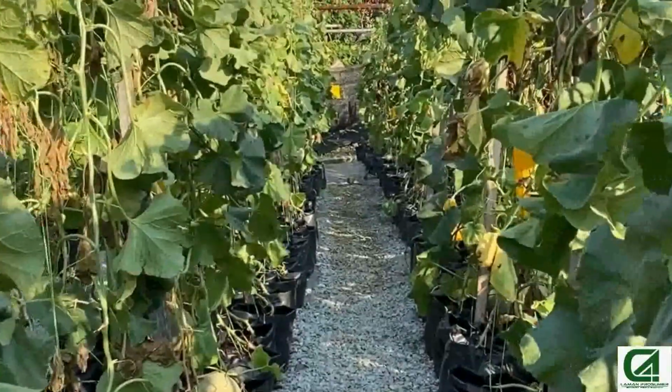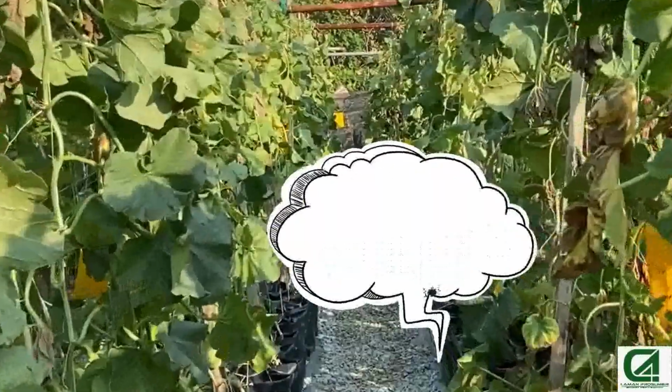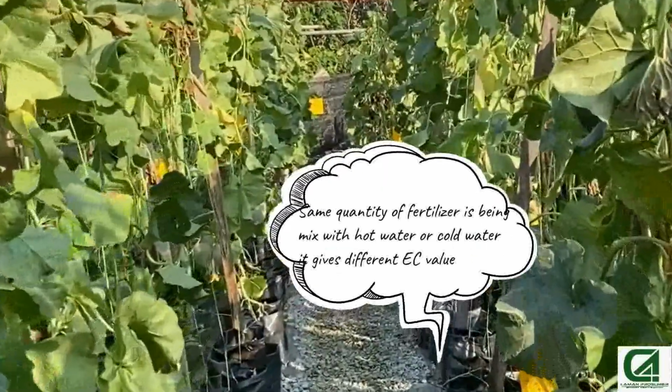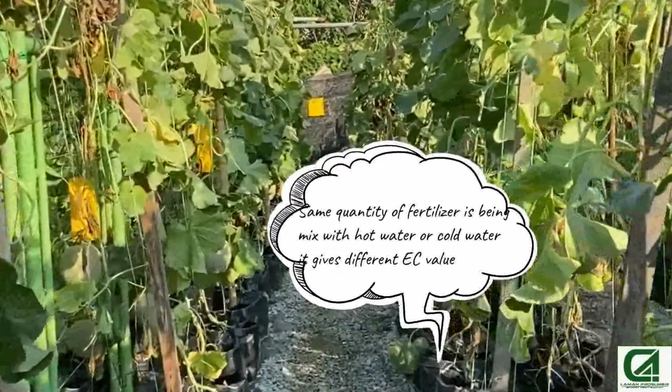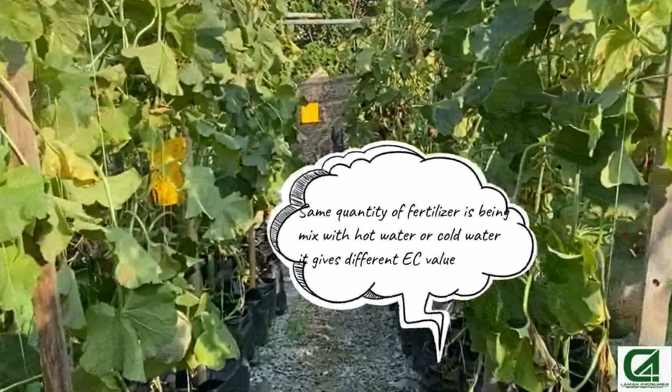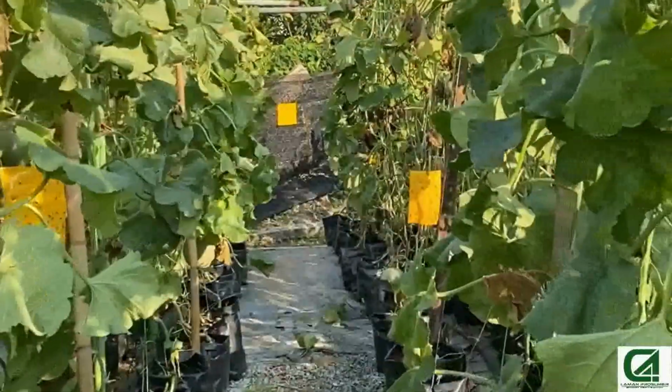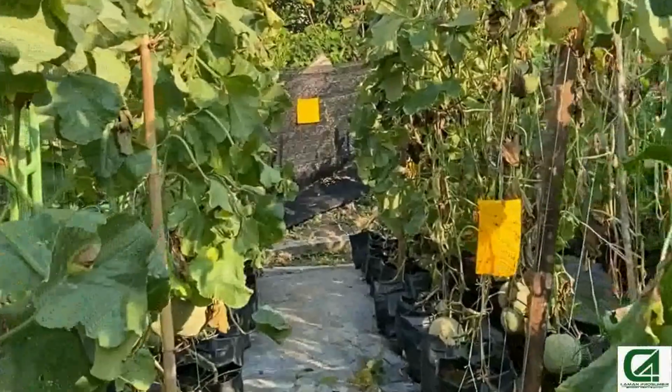Did you know that when the same quantity of fertilizer is mixed with hot water or cold water, the two solutions produced will give different readings of EC value? Temperature compensation prevents this situation from happening.